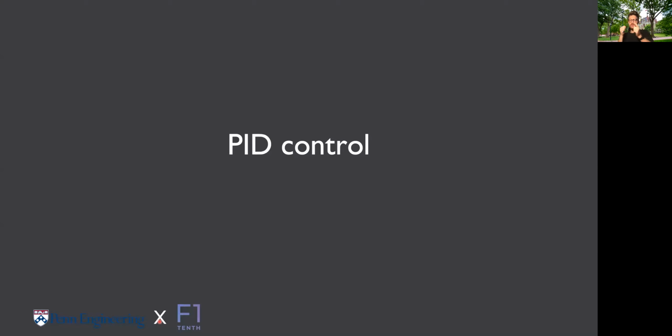You have to remember how to set up your control system, which means you have to define for yourself what is the reference signal, what is the control output signal, what is the control input signal. You have to define for yourself where the feedback loop is, so which information you need to feed back into your system. We will learn later with the car that we have to measure additional information to create a much better tracking error, or let's say control error, for our system. This is what you have to remember from part number 1.